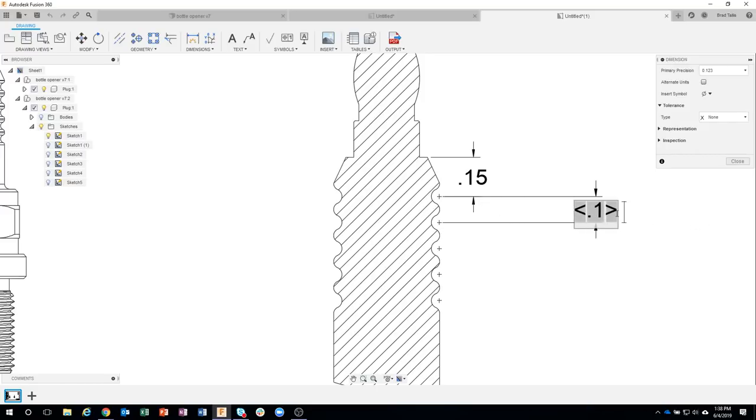Now here is a cool tip. If you want to remember anything from today, it's how do I create a second line? Because if I were to hit enter right now, it would just accept my dimension. Well, to add a second line, you'll hold down shift and hit enter. And notice I'm now down in a second line. So again, holding down shift and hitting enter, I can now come in here and say spacing, for example.